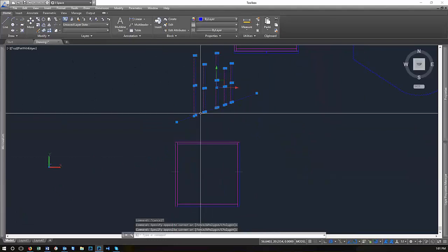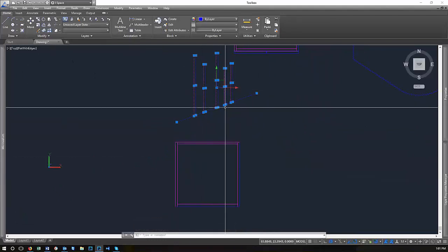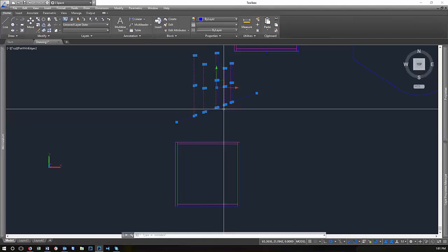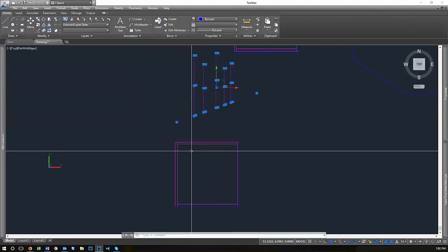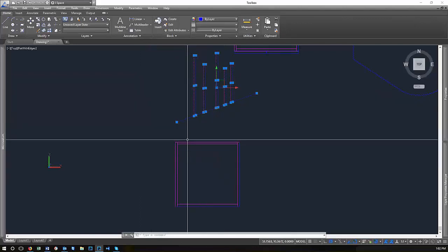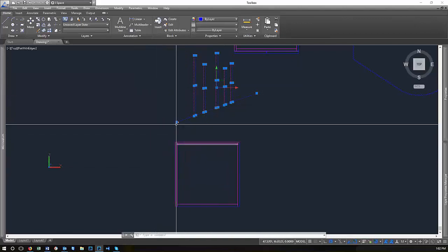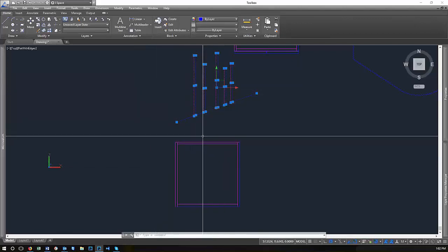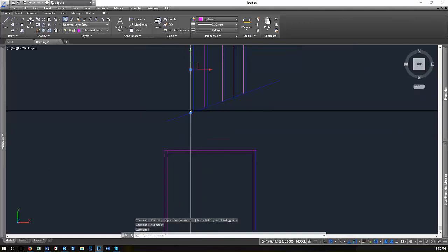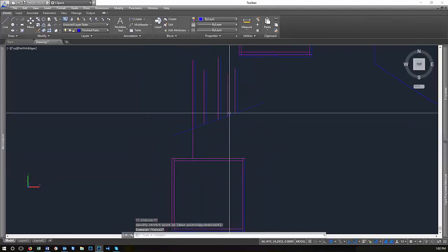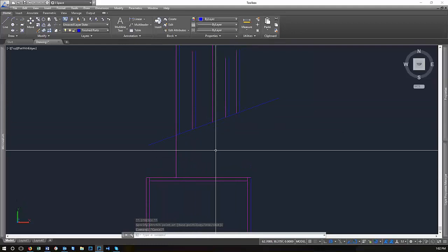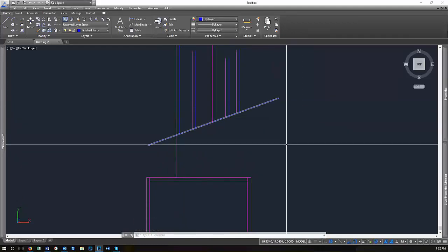It helps because you can start with a line that you already know is on a good axis and is the length that you need. So then you offset, and then you want to extend something to go all the way to another object, get it to intersect, and then you know that you've got a firm connection between these two objects. If you click and drag, it works, but you might accidentally grab the wrong location. So trim and extend are the best ways to go when you're trying to get objects to intersect.